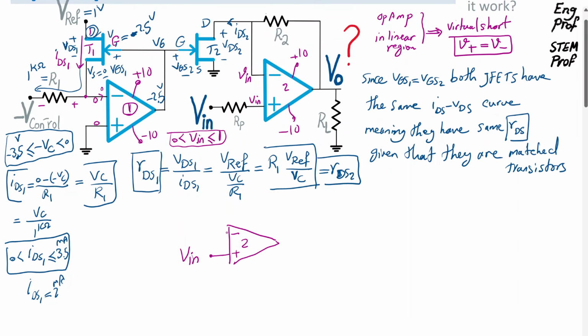And then we have the connection here, R2 to output Vout. I don't care about RL in terms of defining the gain in this circuit, because gain is not defined by RL. Gain is defined by R2 and the equivalent resistance for this transistor. So for that transistor, I'm going to show the equivalent resistance this way: RDS and then grounded. There you go. So this is a simple non-inverting amplifier.